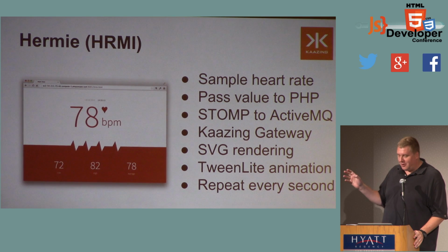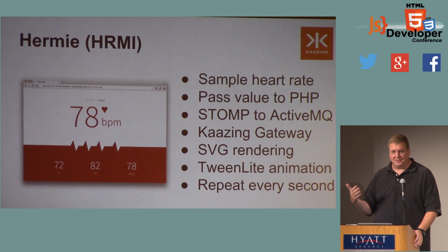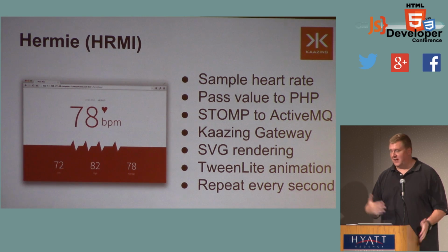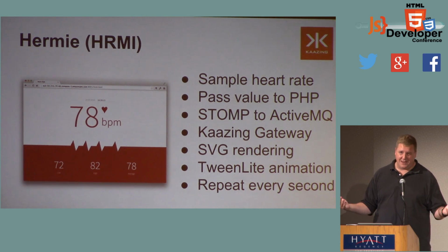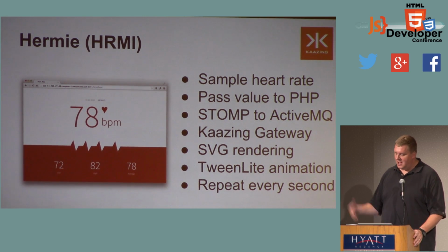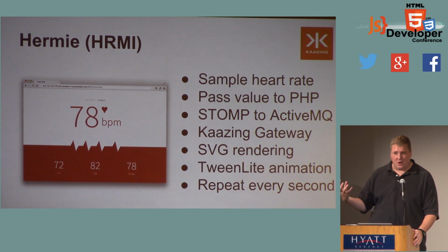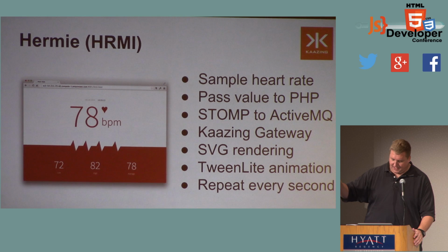It's going to sample the heart rate from that Polar chip. It's going to use a protocol called STOMP. STOMP is a simple text-oriented message protocol. It's very easy to use and implement. There are a lot of libraries and implementations for it. You can write your own. I wrote one for Arduino Yun, and it's going to spit the data coming off of the heart rate monitor into an